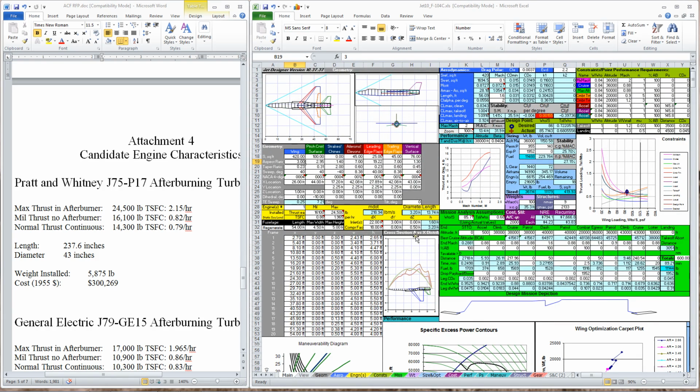But what that did to us is reduce our static margin and reduce our moment arm for our vertical tail. Let's try that trick of increasing the tail's aspect ratio again. It doesn't look too bad the way it is. Increase it, we're almost there. It's a pretty nice looking tail. Let's try 1.6. Almost there, 1.65. That's a pretty nice looking tail. Hey, we don't have any red boxes anymore. I think this airplane is just about ready to go into production.